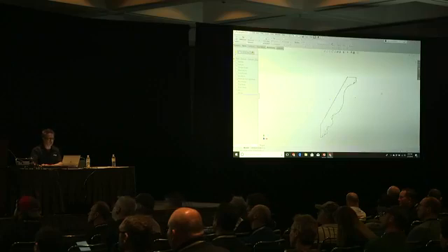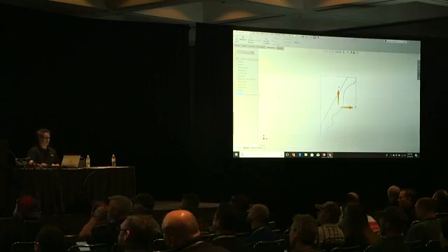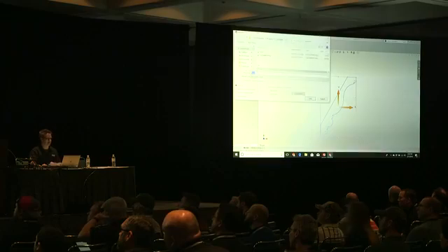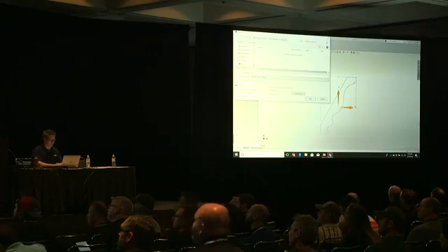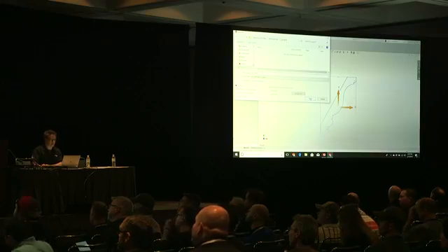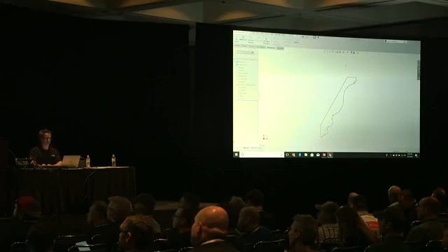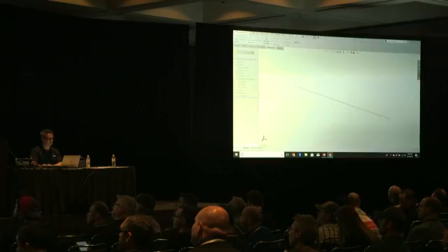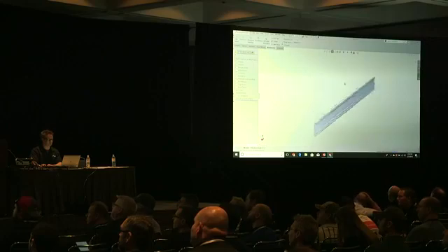So hit D, close that. This is the important part that I often forget. I'm very proud of myself for remembering. Select the sketch, say File, Save As. We're going to save it as a library feature part, and I'm going to drop it into my weldment profiles. It was HC 1014 or something like that, as a library feature part. I will know that I've done this right if there's a little L next to my sketch. So now I can close this. I can add it as a structural member just by changing to that, select the line, right-click, crown molding.